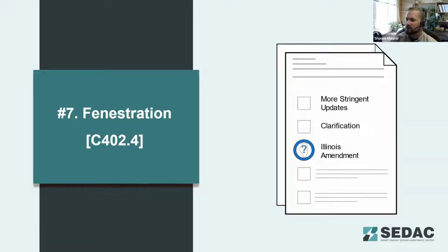And then the last question that we had come in before we close our poll here: assuming U factors equals U values, yes. For the U factors included in the code, I believe those do include air films. Those are coming from the ASHRAE 90.1 supplemental documentation, and those typically do include the air films for those materials. And so you would not count those separately and add them into those required U values.